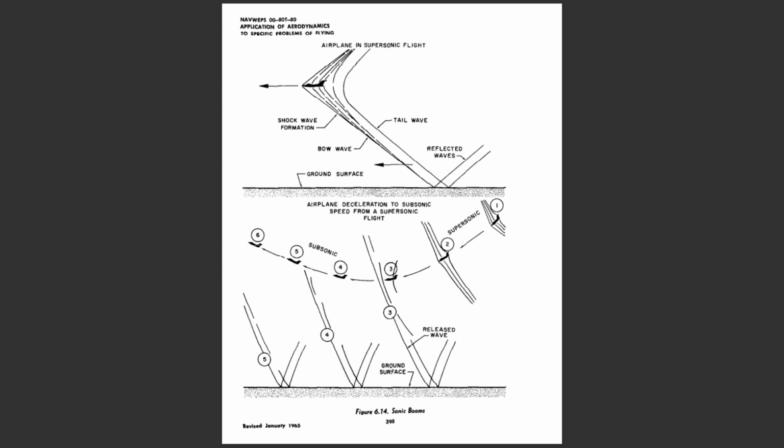When the airplane is in level supersonic flight, a pattern of shock waves is developed which is much dependent on the configuration and flight Mach number of the airplane. At a considerable distance from the airplane, these shock waves tend to combine along two common fronts and extend away from the airplane in a sort of conical surface. The waves decrease in strength with distance away from the airplane, but the pressure jump remains of an audible intensity for a considerable distance from the airplane.